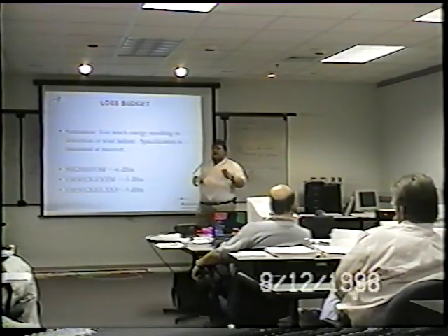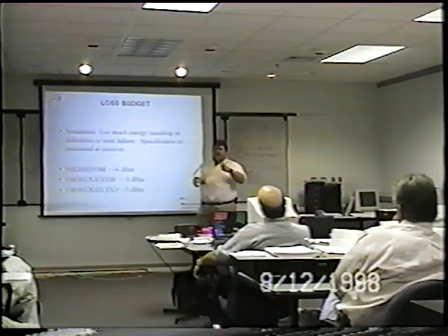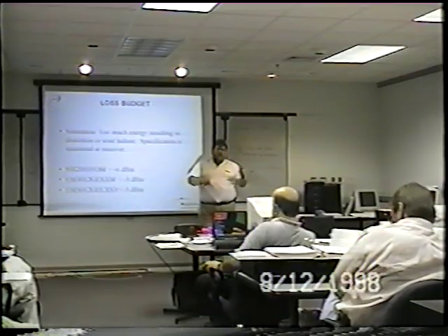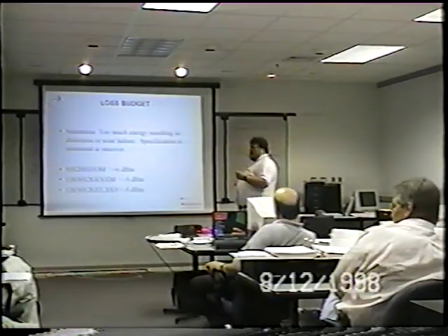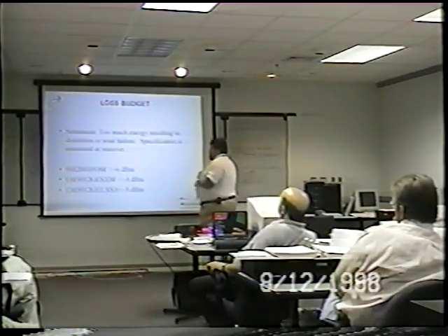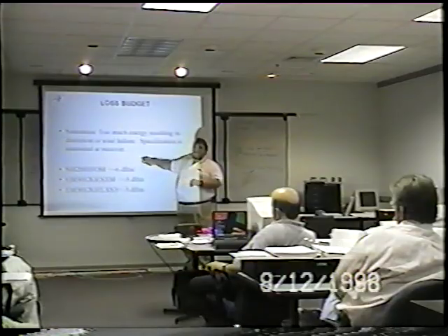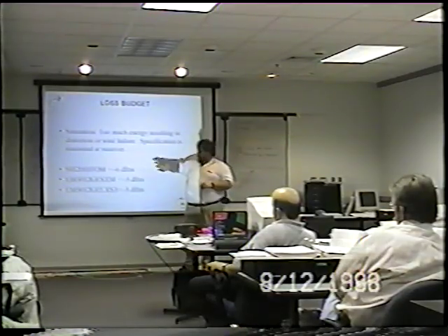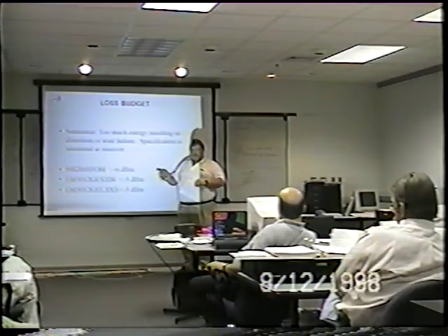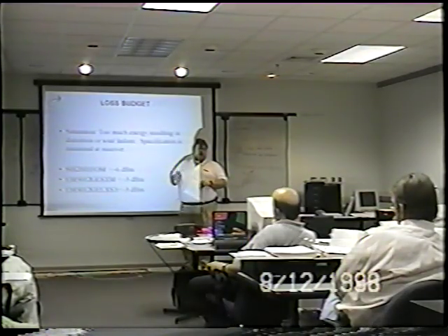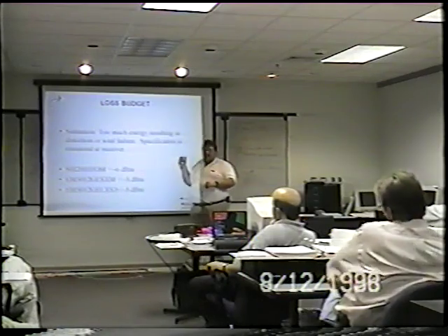Those are typically inline devices and values of 5 dB or 10 dB. They're typically in 3 dB increments, 3 dB, 6 dB, 9 dB, and so on, which you can pad it down, if you will. Which brings up another concern. Just make a note that if you're padding at 850 and 1300 nanometer, you're okay. Padding gets a little tricky at 1550, especially if you're padding close to the emitter.